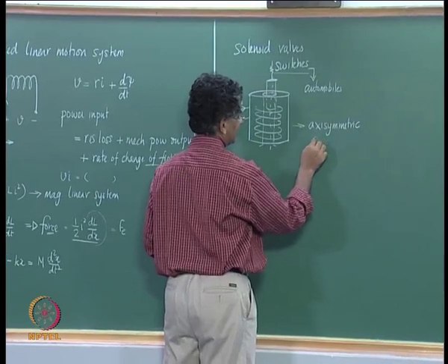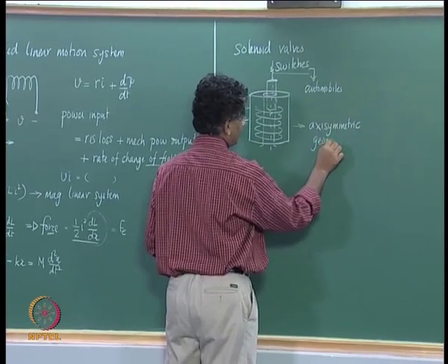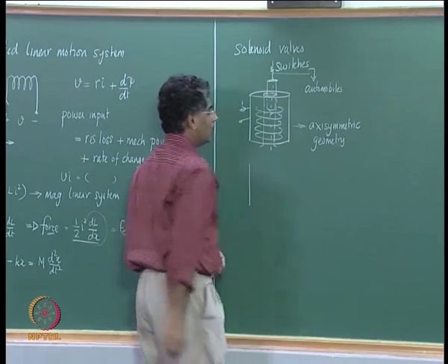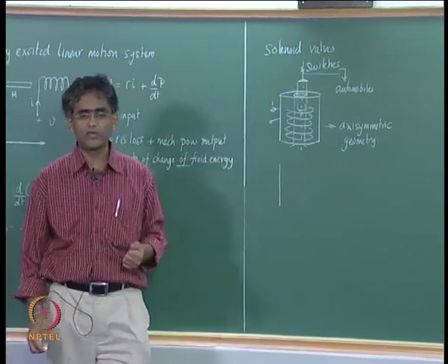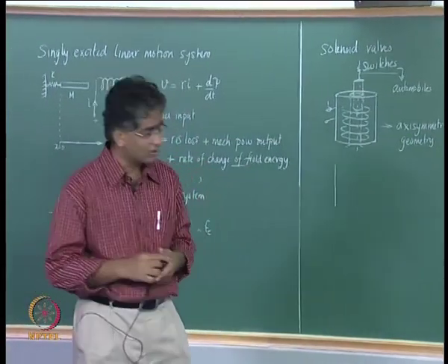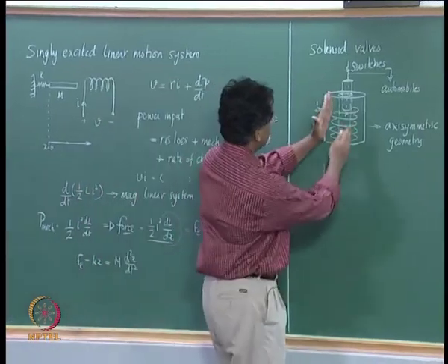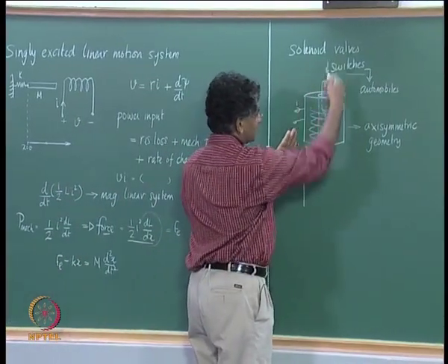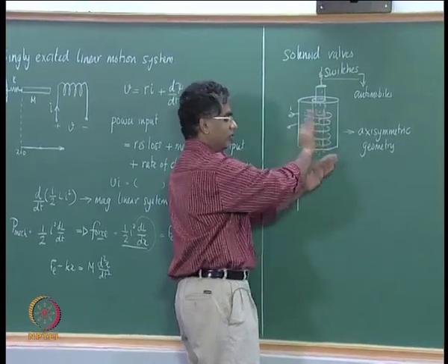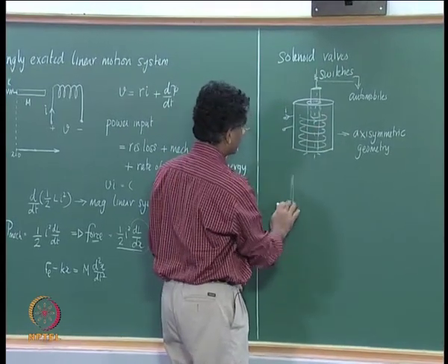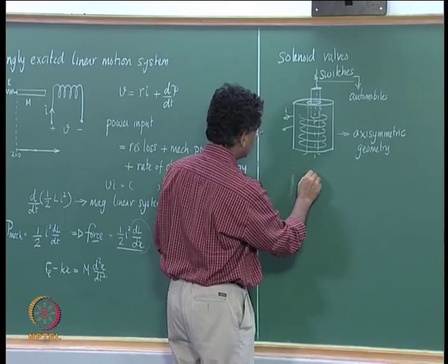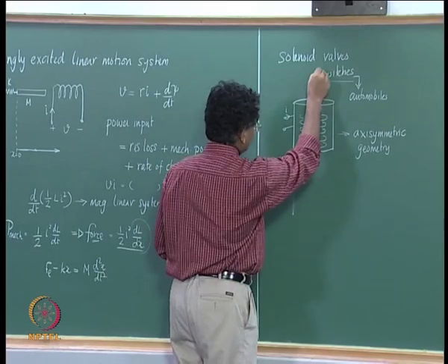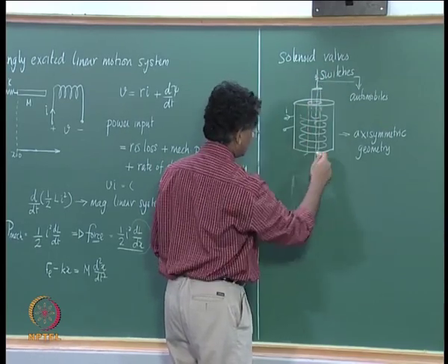It has an axisymmetric geometry, and in order to do an FE analysis of this, most FE software allows us to model only one section of this, which is assumed to be swept around, and therefore it may be enough to represent the section which is seen in the middle.